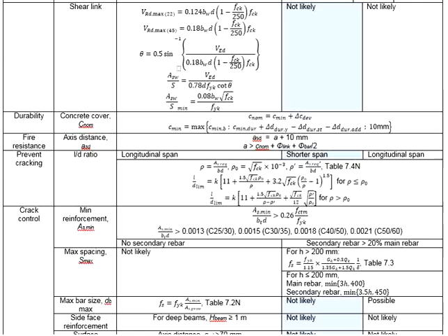In checking for the minimum reinforcement bar for secondary rebar, you need to make sure the As,min equations, the ratio, and this 20% of the main reinforcement bar are all complied. To make it simple, regarding the minimum reinforcement, no matter whether it is main reinforcement or secondary reinforcement, the equations and the ratio must be complied.